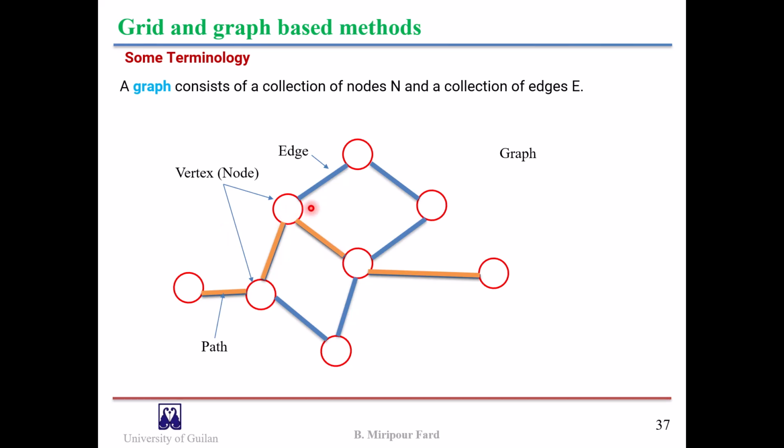So a graph consists of a collection of nodes and a collection of edges, and an edge connects two nodes. In motion planning, a node typically represents a configuration or state, while an edge between two nodes indicates the ability to move from one one to another without penetrating an obstacle or violating other constraints.